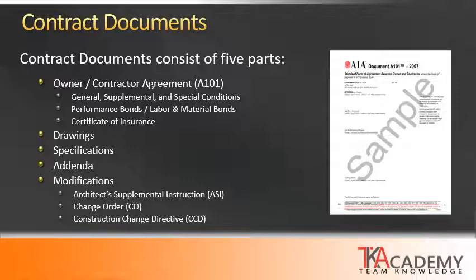The important thing to note on this is that the addenda must be distributed to all bidders. So if you're receiving questions, if a subcontractor calls and asks for a specific question on an issue, it is not advised to answer that directly. It is better to answer it in a published addenda and send out to everyone who is bidding it, so that there cannot be any disputes on having equal access to information or showing favoritism to any one bidder.